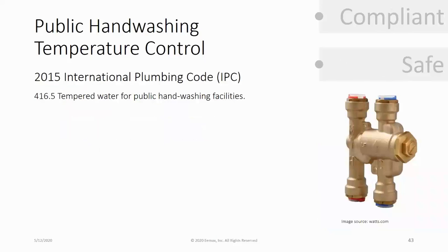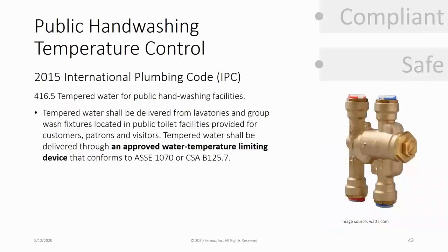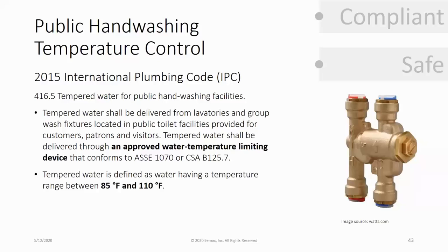2015 IPC, they define tempered water as a requirement. The tempered water still had to be regulated through an ASSE 1070 rated mixing valve, and tempered water is defined as having a range between 85 and 110.